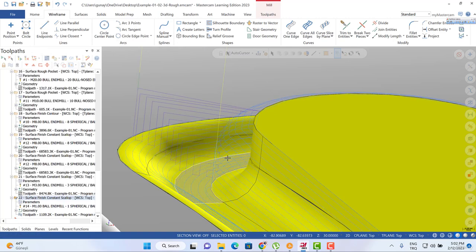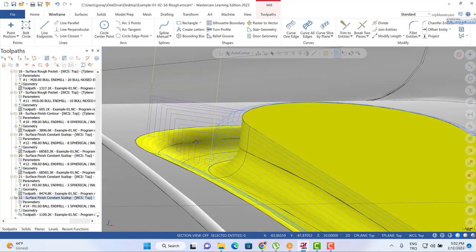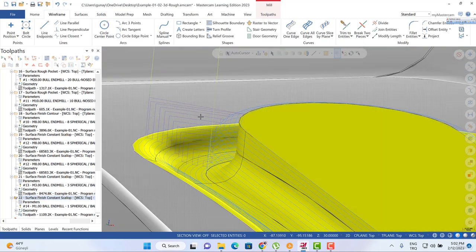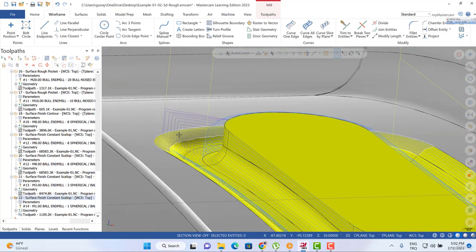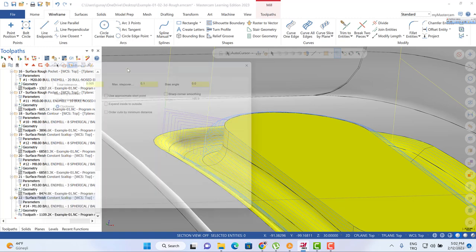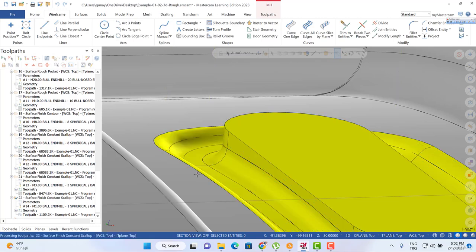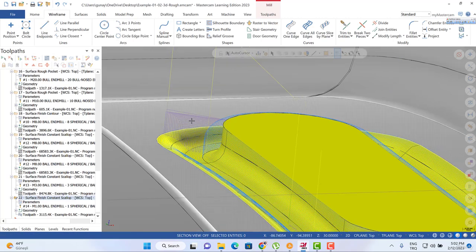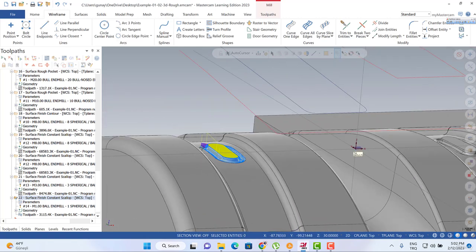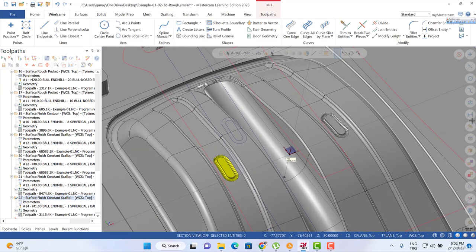You know that to be able to create that kind of toolpath, actually we're going to see our transaction position here, and then we also need to change our step over. You know that when you split your product, for example, according to this area and this area, that's also going to help you to change different step over, different cutting strategies, different feed rate and different tool as well.